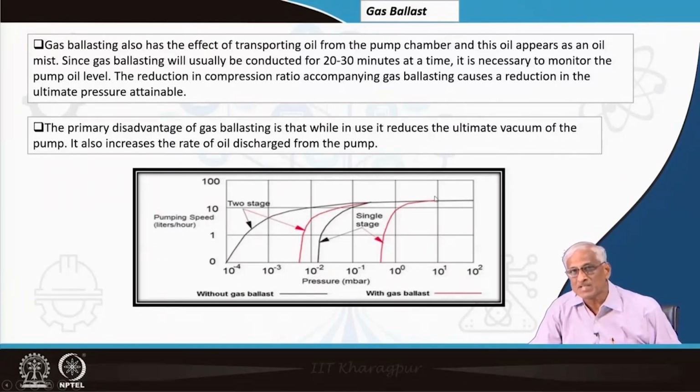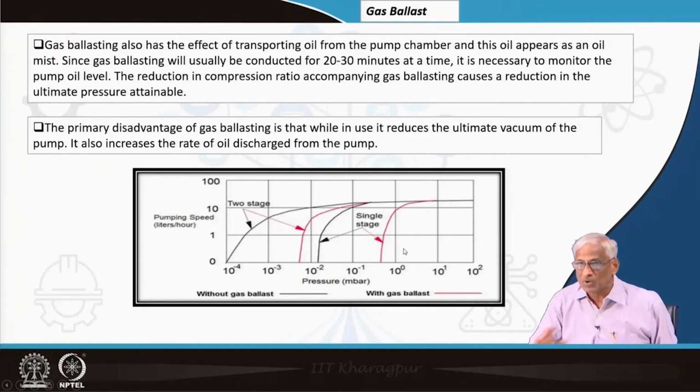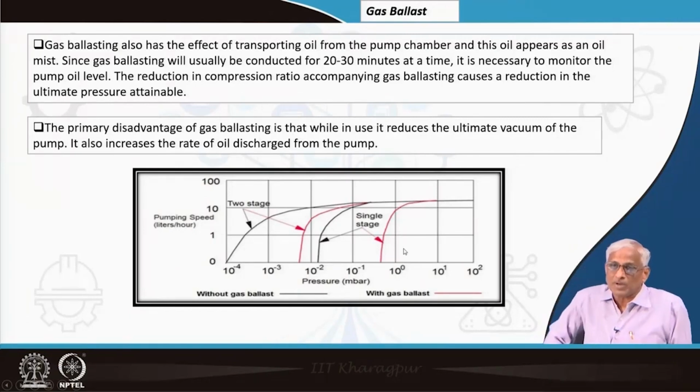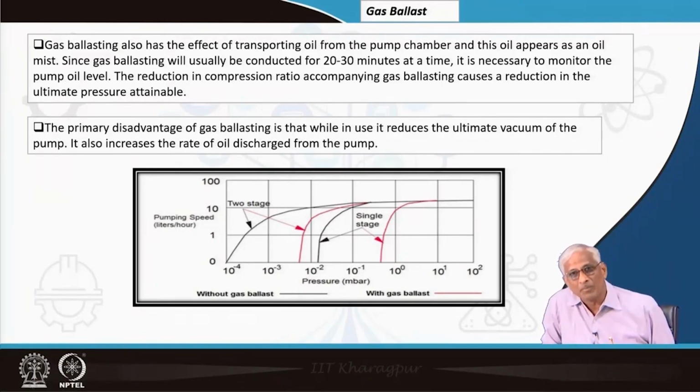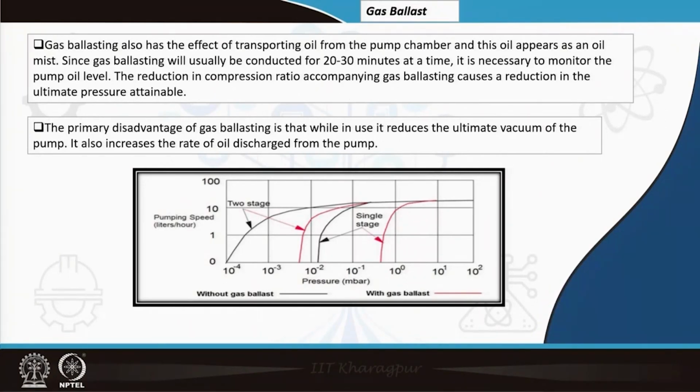So, pumping speed variations are very important issues in rotary vane pumps, where the engineer has to properly design depending on the application. Okay. So, advantages, disadvantages, pumping speed variations with and without oil, so many aspects are there. In fact, in the last 20 years dry pumps have come, that we will see in the next section, replacing these in certain very important applications where oil is not allowed, water vapor is not allowed. Certain things are coming up like that in pharmaceutical sectors.